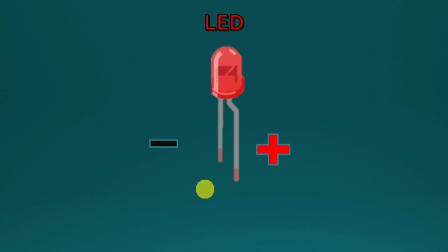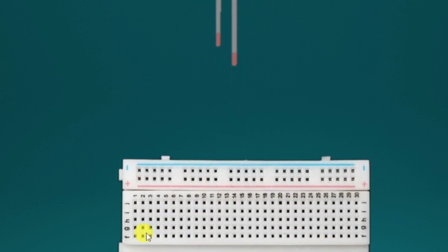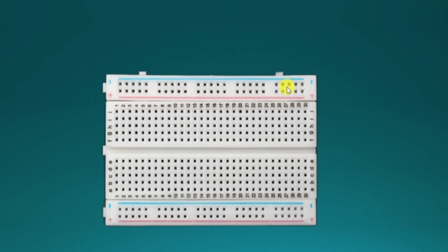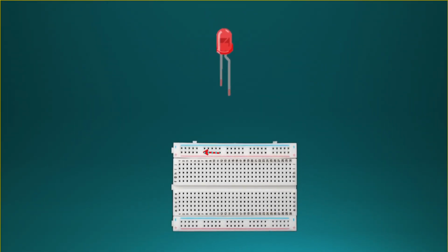As we saw, the hardware connection is made using a breadboard. So when we are making the hardware connections, a breadboard will be preferred over the zero PCB. Inside the breadboard, there are outer points and inner points. The outer points are shorted horizontally, and both sides of the outer points are shorted horizontally, whereas the inner points are shorted vertically.